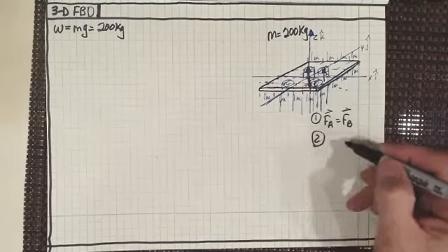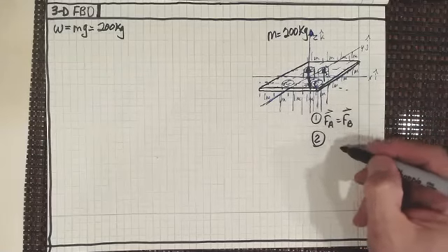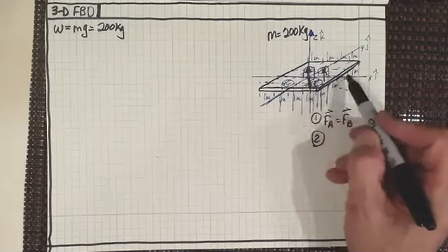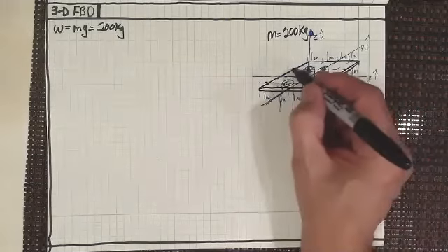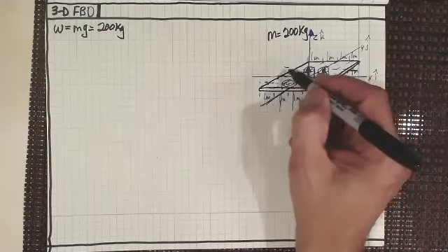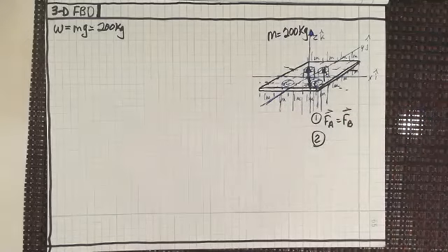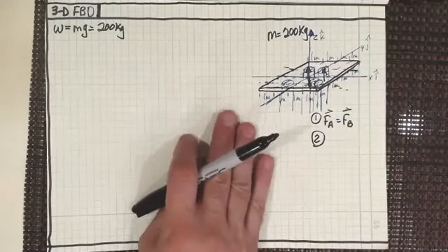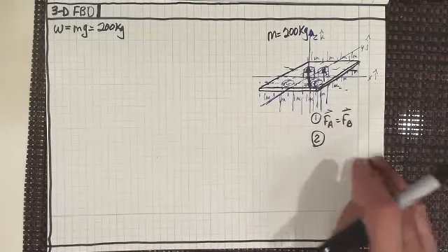The second one is that column B takes all of the weight, right? I'll write that out later. I shouldn't say all the weight, but all of the weight that these columns are going to take, because as I said, C is going to be along 1 meter, and you can see these columns are set 1 meter off the end too. So we're going to sum moments about that center axis and this axis, and we're also going to sum them three-dimensionally, and it comes out to the same thing, only it's a little more robust notation.